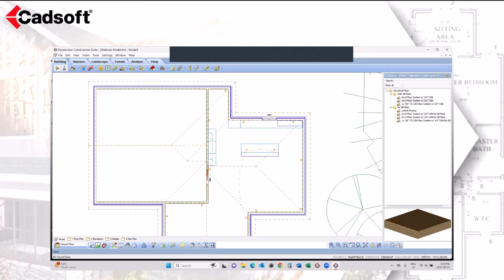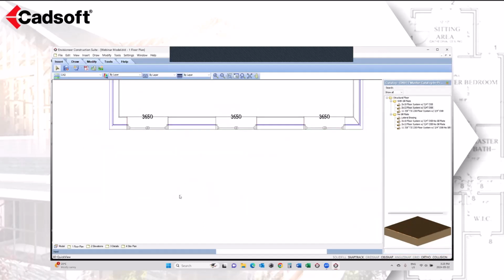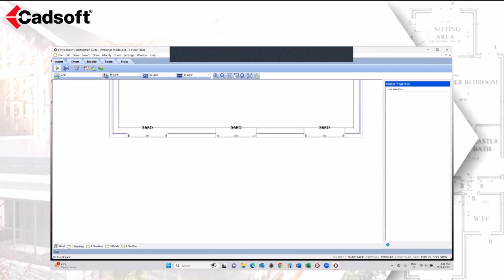When we go to create our working drawings, it takes a 2D view of our model and it puts it out onto our working drawing sheets. And when it does that transfer from the model onto our worksheets, and if I flip out to a worksheet right now and I've got a view out here, it changes them and puts them all on different layers. So every line in here is a different layer. And you can see up here in the left-hand side that as I pick a different part of that wall, it changes what layer that is.